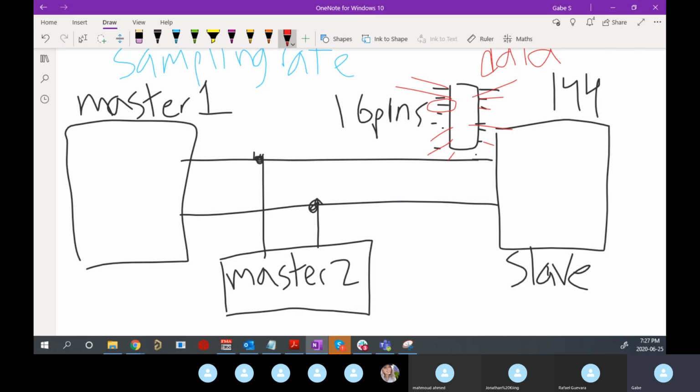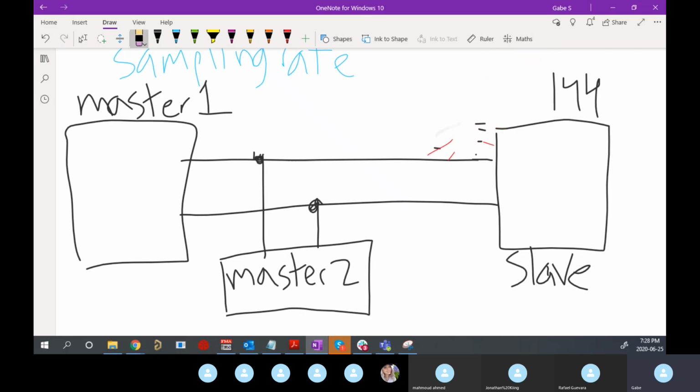So there's a weird scenario in I2C where you have multi-master mode. It's not very common, like I alluded to earlier, but it does happen. The question now is same as before, sort of what John was asking. What happens when they want to, and now you don't have a rogue sensor. This is a totally legit case, right? Master 1 wants to talk and Master 2 wants to talk. They should theoretically both have equal say to the bus because they're both masters. So who wins, right? Who gets to actually talk first?